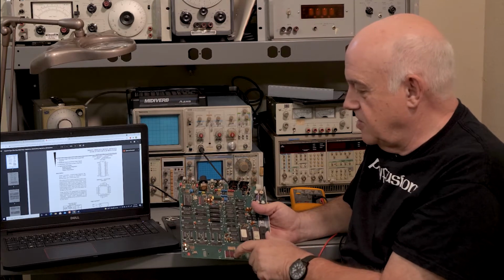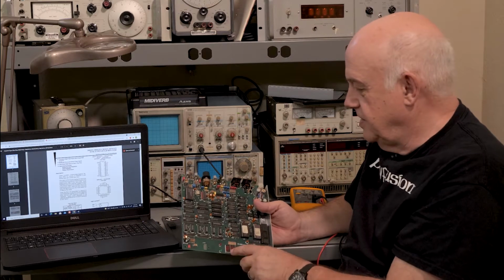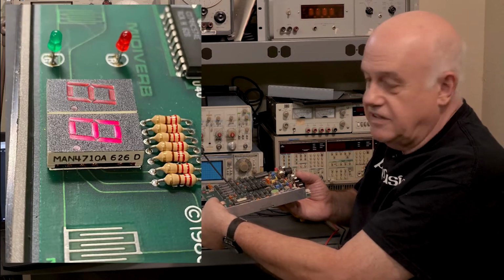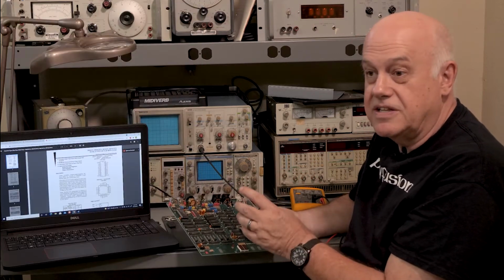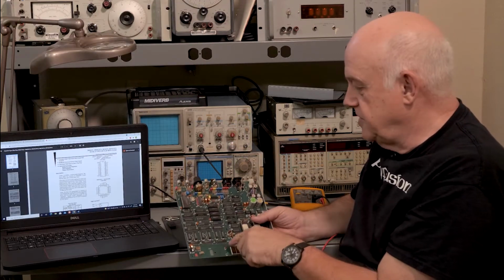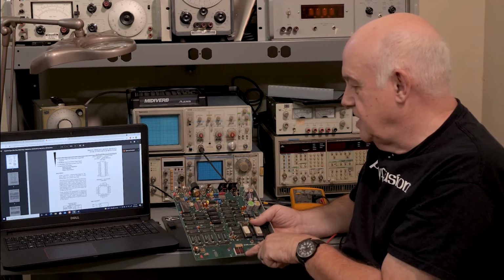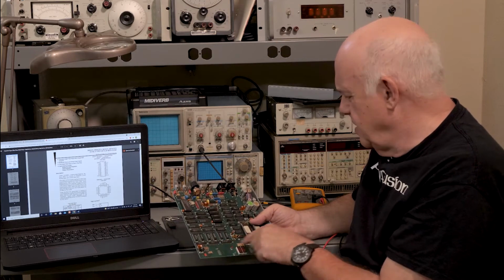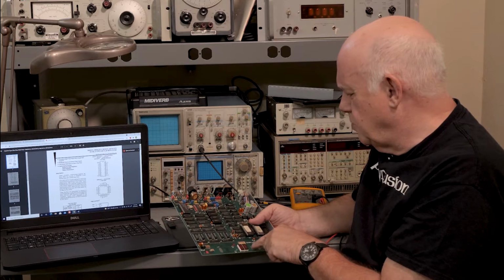How does it turn on the LEDs? Well, they're multiplexed. You have resistors. You can look at the part number for the LED right there. It's common anode. So that means that the anodes are tied together and you turn each segment on by pulling the cathode down to ground. All right. Usually there's a transistor to do that, but over here there's not enough transistors. So I wonder what they did.